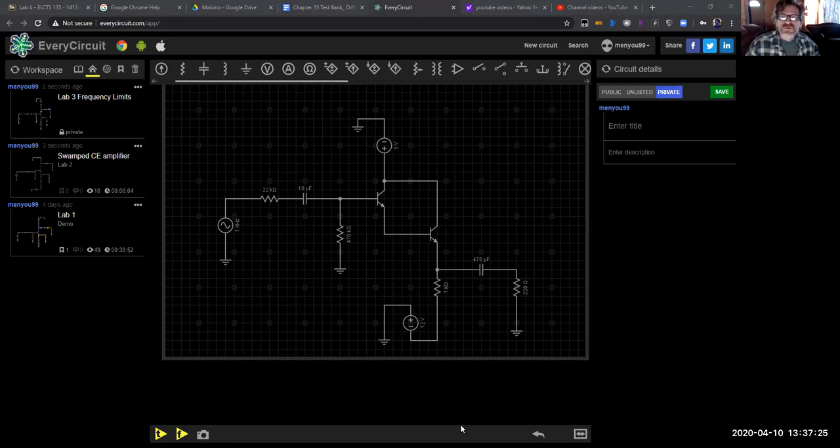I have you go through and, of course, we're not using a transistor curve tracer or a beta checker. We can pretty much dead on have our beta values of 100 for each of them, right? Just check the values of your transistor, and make sure that they are that.